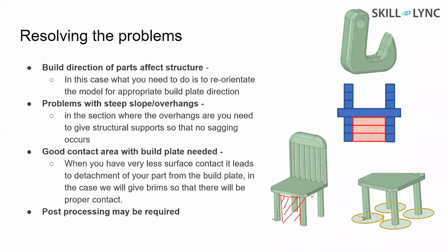In this case, what will happen? This particular material will go down. It will spill, it will go down, it's wasted. So in this case, what you need to do? This is one of the important topics. Then you need to give supports like this. In this particular image, as shown here, you can build supports here. What are supports?